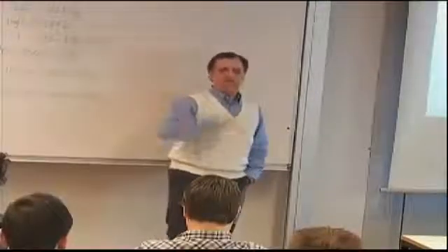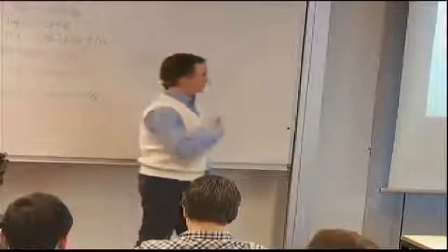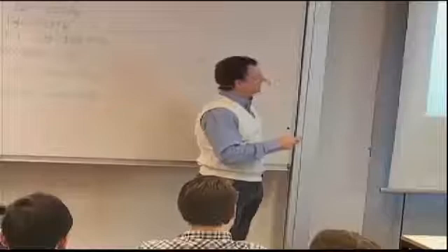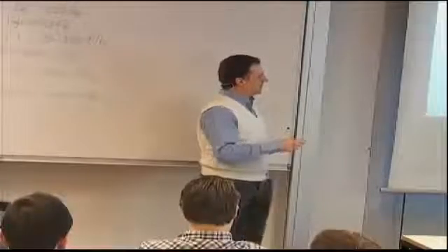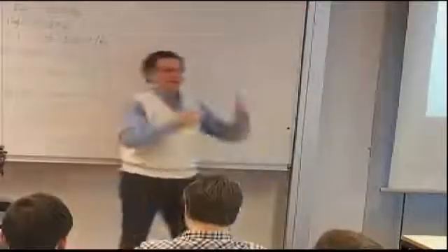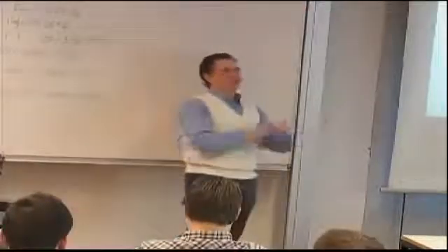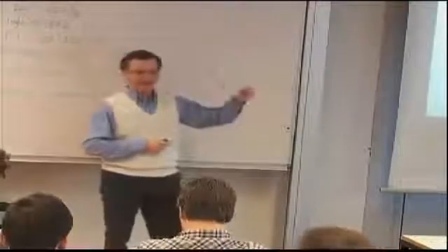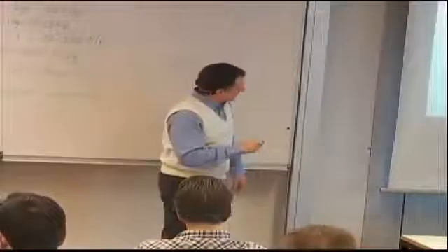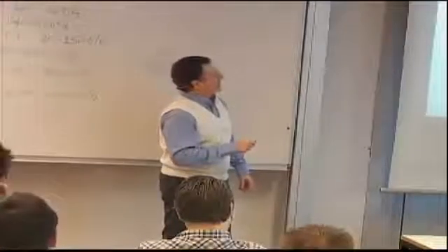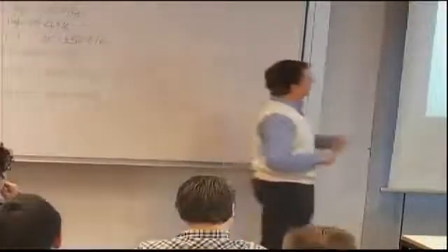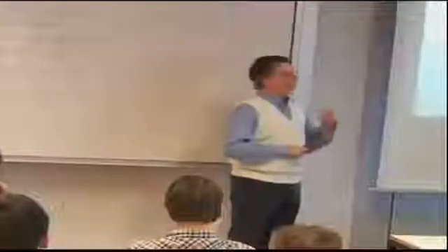And because you cannot see it and repair it, you have to live with it, which means it becomes an ultimate load requirement. Typically, the inspection method or the detection method is based on visible inspection, which is another interesting story. How many people looking at the same thing will arrive at the same conclusion in terms of, oh yeah, I can see the damage there and it's about that size. But that's what we have to live with. So if you choose that the inspection method is visible, then it's barely visible impact damage. So ultimate load for that, and limit load if it's visible damage.